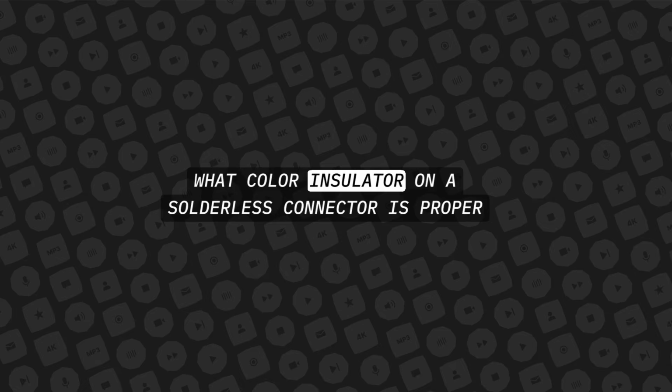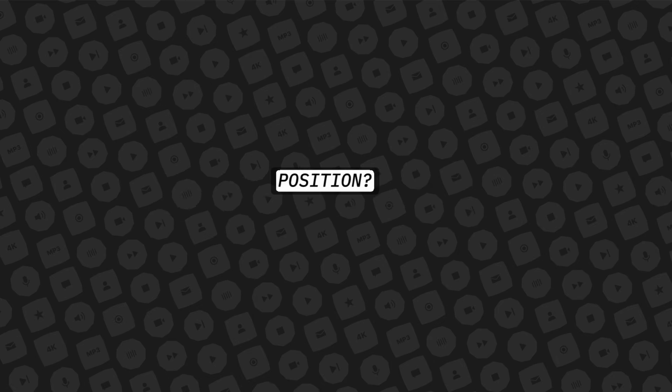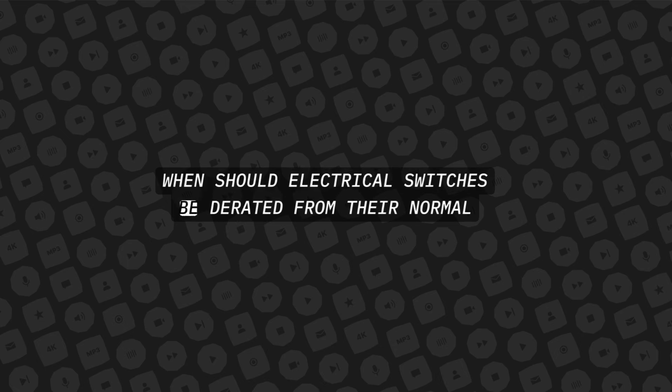What color insulator on a solderless connector is proper for a 10-gauge wire? Yellow. How should electrical switches typically be oriented in the on position? Up or forward. When should electrical switches be derated from their normal current rating?